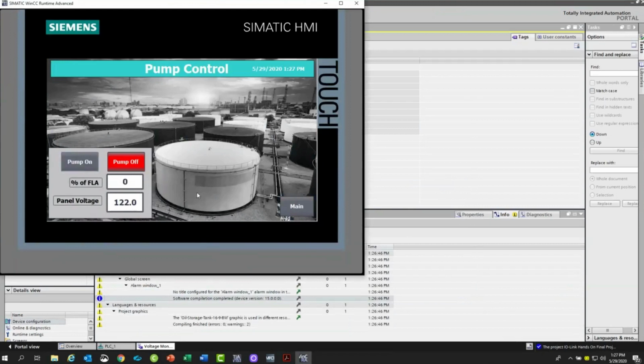If I flip this switch here, it takes away that single phase voltage, and you'll see not only will the voltage go away, but I would also get the diagnostic bits telling me that it's out of range or below range as well with that system. I can also come in here and start and stop the contactor from the overload relay via this screen.